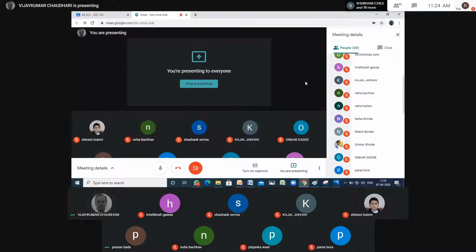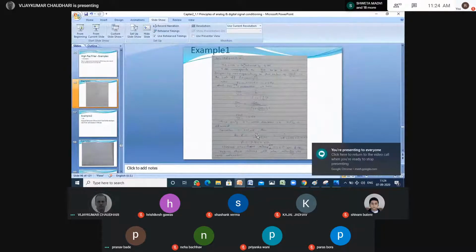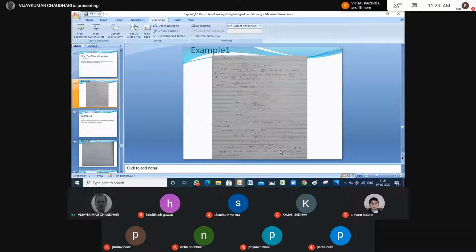No, no. It should not be, because what is the difference? What we have actually found is 7.95 and I have given 7.5. There should not be much difference in frequency. Frequency is 2 kilohertz, so it will be slightly less or more than that. So that standard value 7.5k, that's resistance, right? Instead of 7.95, you have to put 7.5 for the first case and 8.2 for the second case.